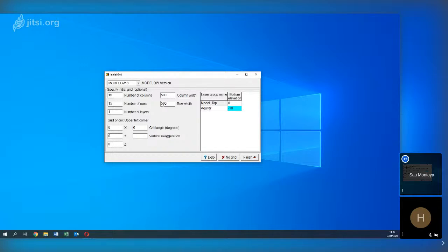So, will 500 meters be right if you are dealing with a local scale, on the scale of a town? No, maybe not. But if you are dealing with a region, like if you want to model a province or a state, yeah, maybe you deal with 500 meters, with refinements of 500 meters and refinements of maybe 5,000 meters.